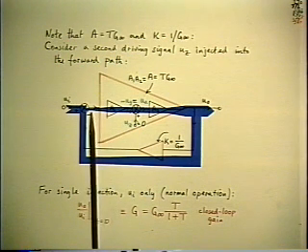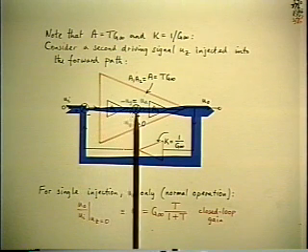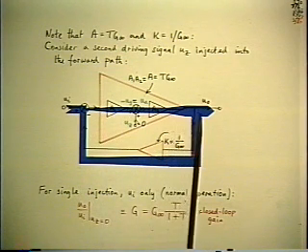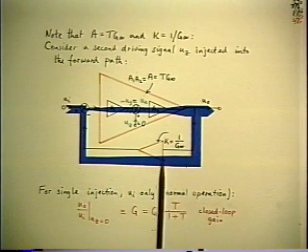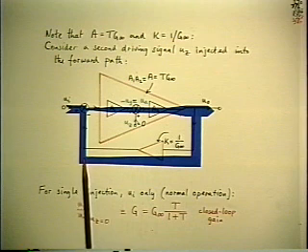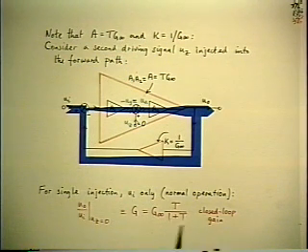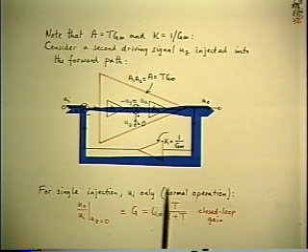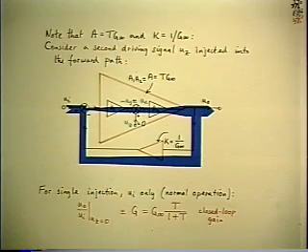So here you have a small error signal which is amplified in A1, goes straight through, gets amplified again in A2, provides the output and the fed-back signal, which is attenuated and subtracted from the input to give you the small error. So that summarizes normal closed-loop operation with the single input signal UI.